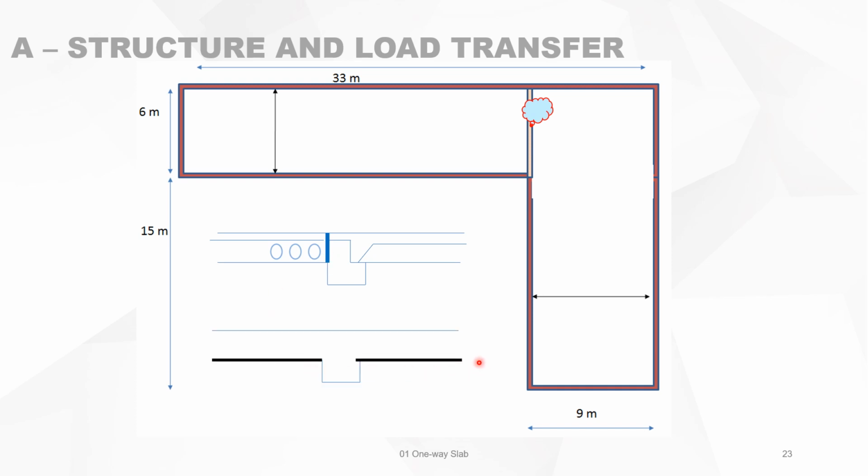In practice, when you have, for instance, a wide slab, precast with lost shuttering, then you can make this continuous. So in this corner, it will not be purely a one-way slab, but we solve it by putting some reinforcement on the top of it.